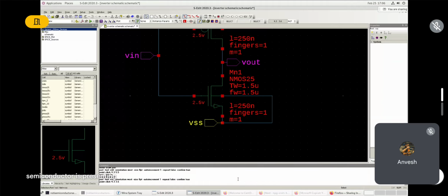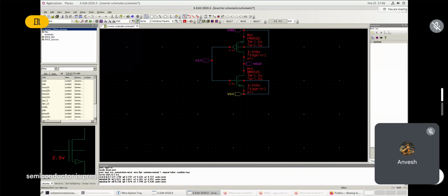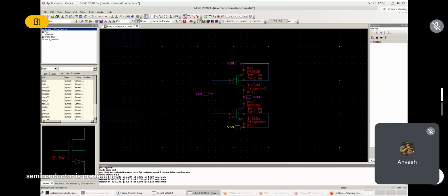So here I have added the connections. That also you can take. Since it's an inverter, it's not necessary. In case you are doing some complex circuit, it may require some functionality. At that particular time, I will not directly run the simulation. I will form a test bench now. I will convert this to the inverter and generate a symbol. And for that symbol, I will add the VDC, pulse. Because voltage should go, right? If I give the voltage only, I will get the functionality through simulation.